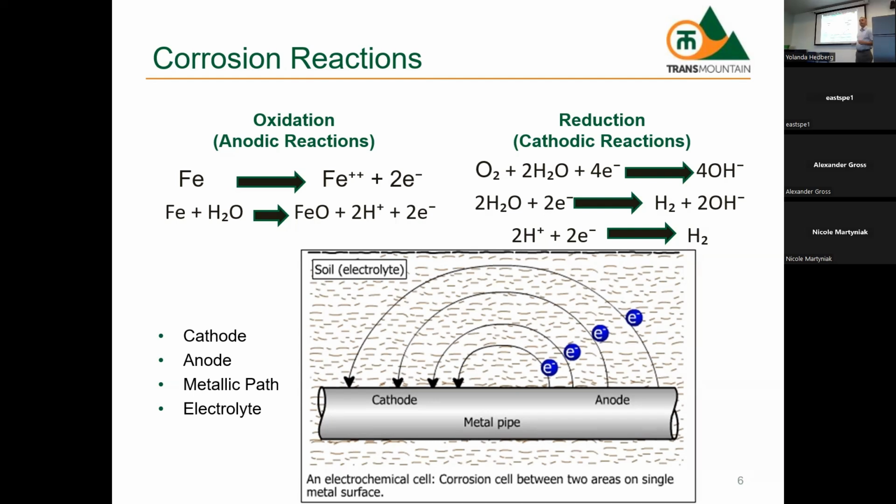But in galvanic corrosion, you can only do that in an environment that has no flow, because when you have flow, one of them could deposit on the other. That happens in water pipelines or in the mouth. For example, with amalgam and gold, if they are far away, the gold can deposit on the amalgam and still cause galvanic corrosion, due to the conductive nature of the fluid. Exactly, because some is solubilized and then redeposited.